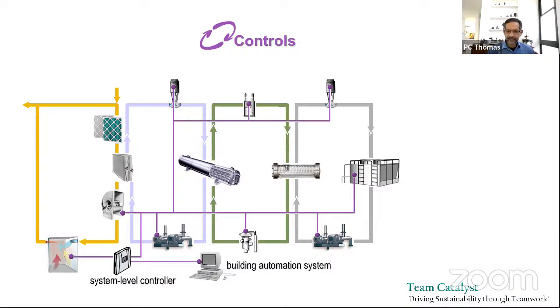So what's an energy efficient air conditioning system? One that can back off the capacity in an efficient way. So when you only need 20 tons or 50 tons, if your air conditioner can work more efficiently, then that's an efficient air conditioning system. That's different from an efficient building fabric.